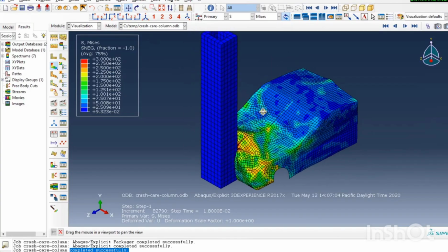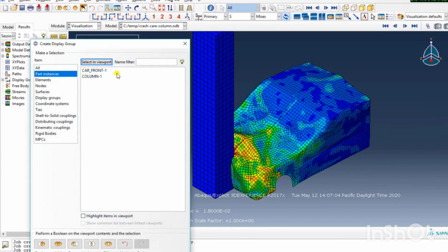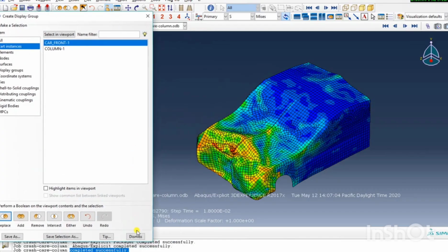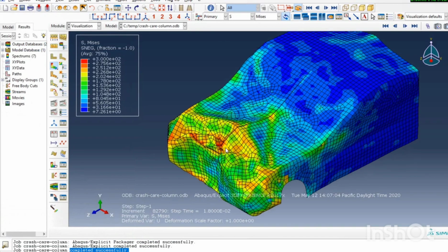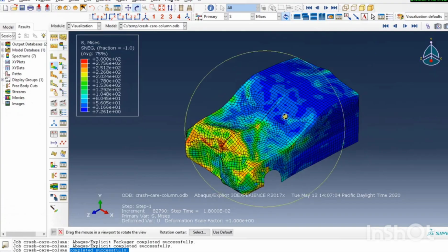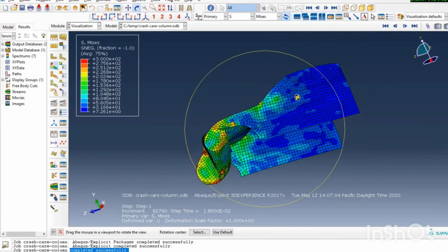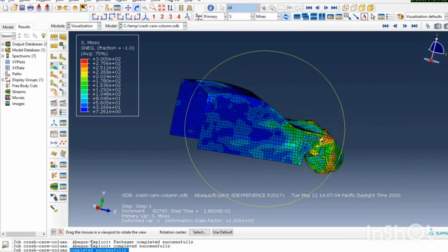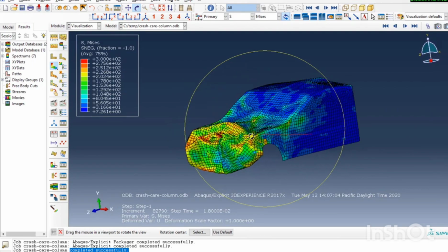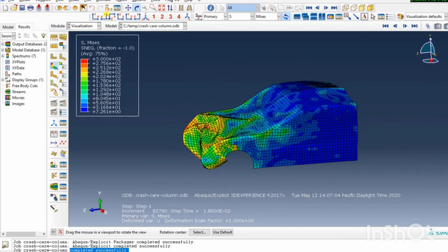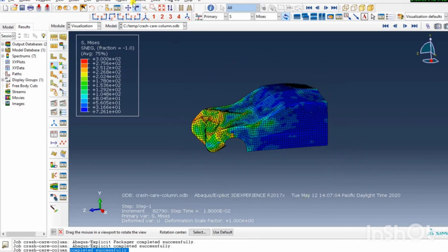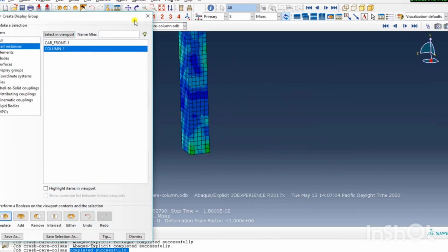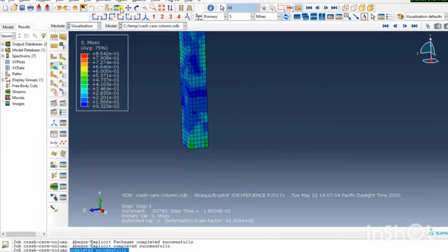If I were to talk about the Abaqus explicit solver, it integrates the equation of motion using a central difference method. The time increment is governed by the smallest element dimension and the wave propagation speed within the material. As a result, it is extremely helpful in managing the small time step, and it is very helpful in maintaining numerical stability.